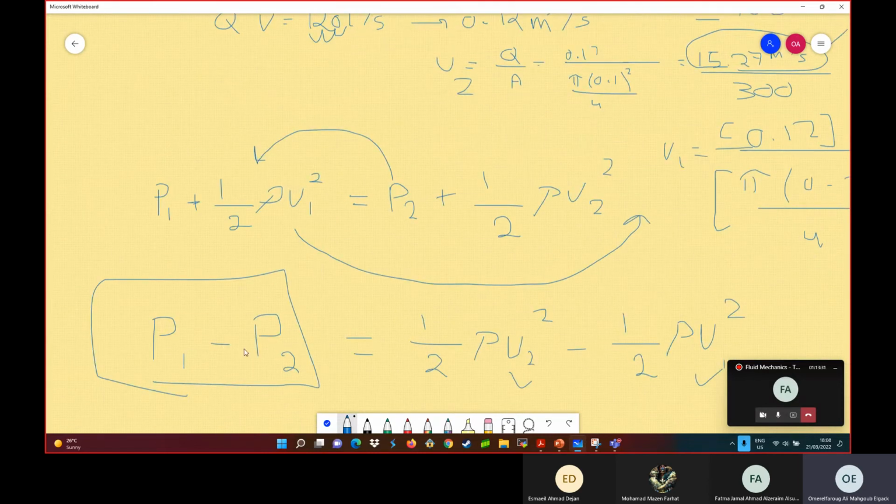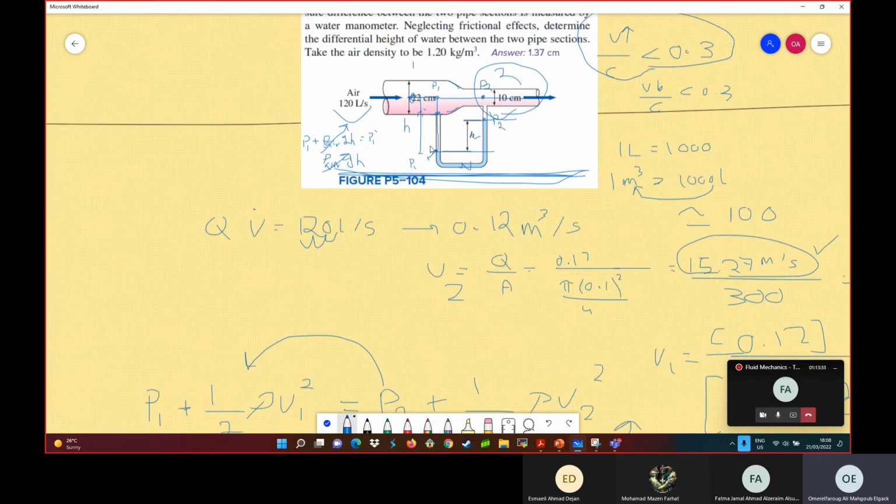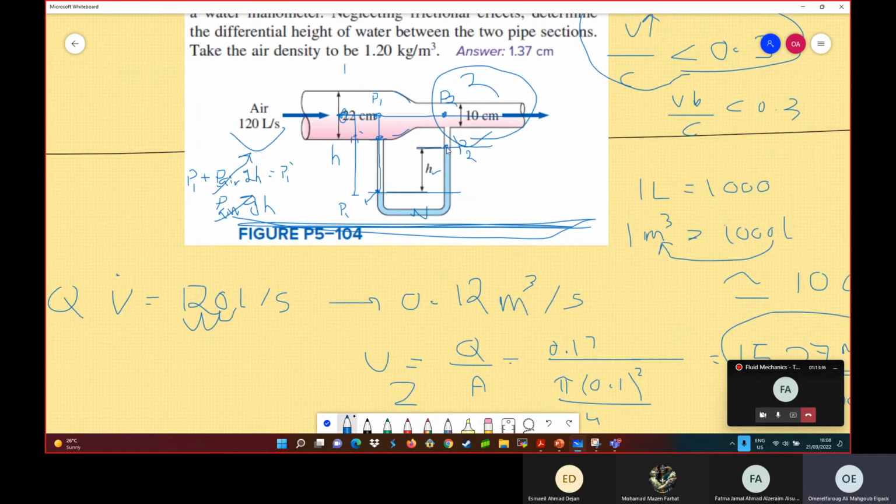Now we can rewrite this equation. Just like you learned in the chapter, maybe chapter 1 or 2, I don't remember, you took the manometer relation, how to go through the manometer and develop pressure relations. So assume I start from here. I have P2, then I go down. I need to add pressure, because more weight of the fluid is now above me, plus rho of the water g h.